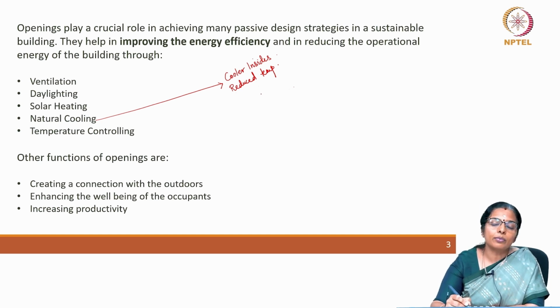These things may look like basics, but it becomes important when you start reading about, or when you take up courses on active, simple passive and advanced passive systems, where nocturnal ventilative cooling is based on this. This is the basic for it. And so, if you want the indoors to be cool, then you use windows to bring in the cool air inside, especially during night.